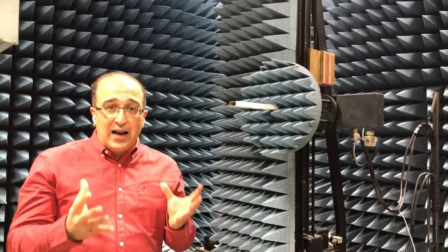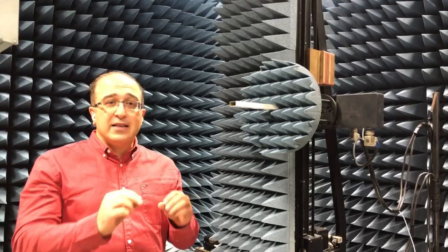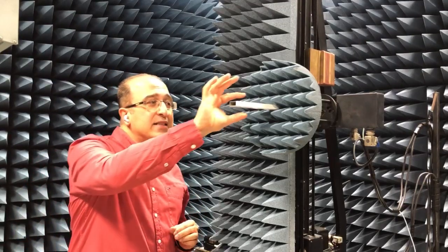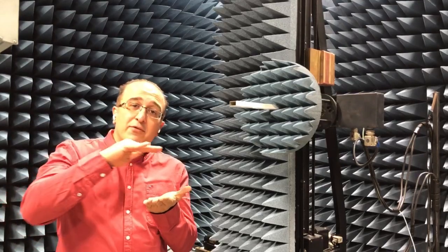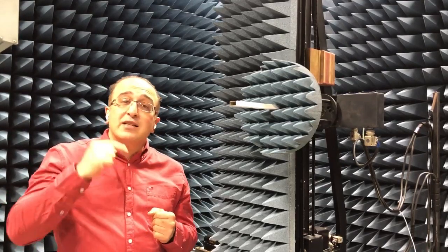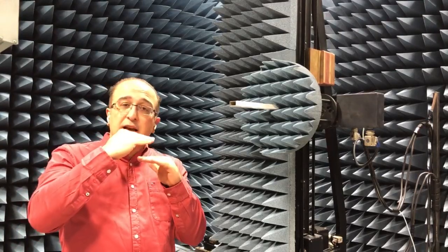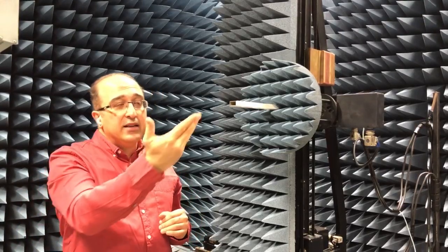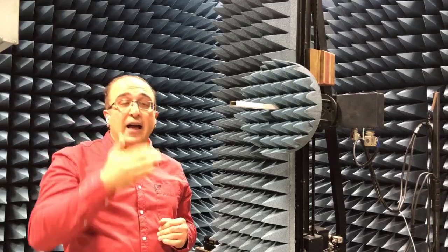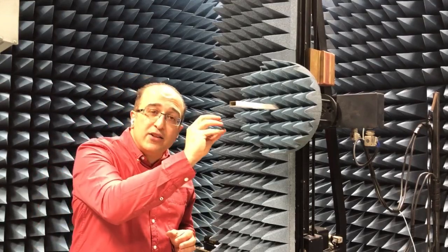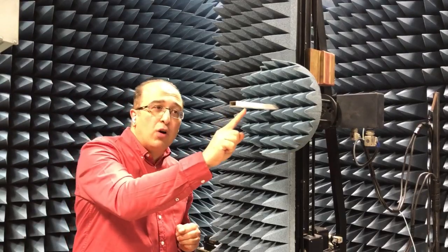So as most of you know, a waveguide is essentially a hollow tube. In this case, this is your hollow tube. As opposed to a standard transmission line that we studied when we had two different metallic wires, or in the case of microstrip antenna, we had the ground plane and then we had a strip that was our second conductor, this is essentially one piece of conductor, which is in this case a hollow tube with rectangular cross section, and essentially it guides electromagnetic wave toward its length.